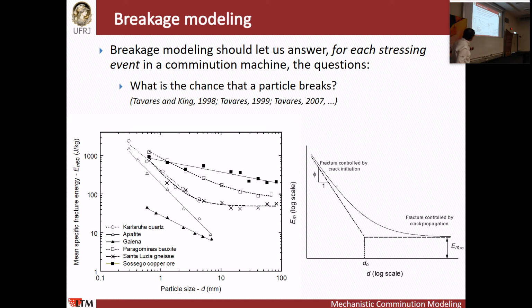In fact, if we borrow a little bit from fracture mechanics, we can go a little further in trying to explain what happens here, which explains why this increase is so steep at fine sizes. We understand that cracks are the ones that define fracture initiation. Whereas at very coarse sizes, you're dealing with very complex particles, and crack initiation is not an issue. It's actually propagation of cracks within the microstructure that eventually creates this constant strength.